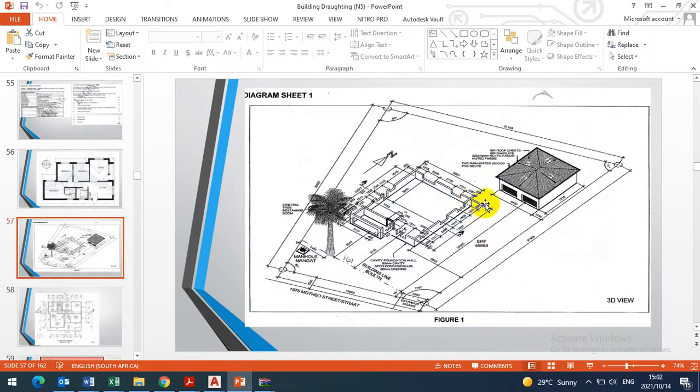This question came in 2017, I'm sure, but it's not difficult. This is a site plan. It came in 3 dimensions. This is your property line. You can see the property line with the angles here. I've already mentioned that when you're doing the property line, sometimes they don't give you the angles. You need to come with a protractor and measure in the question paper what the angles are here, and then you do your property lines.